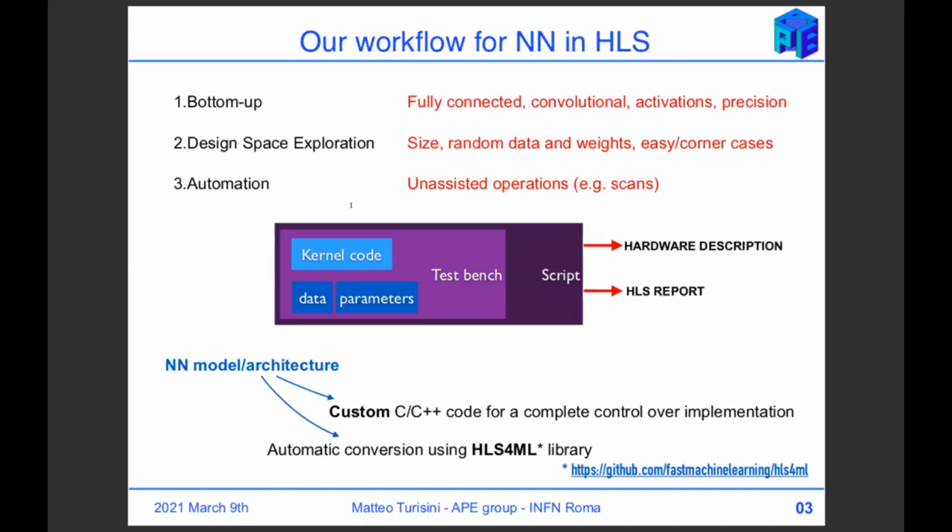So at the very end, you get another description of the circuit and all these reports to analyze. And from this point of view, an HLS library that automates the step between Python and C++ and the custom C++ code are equivalent. Both can be analyzed, compared and checked.